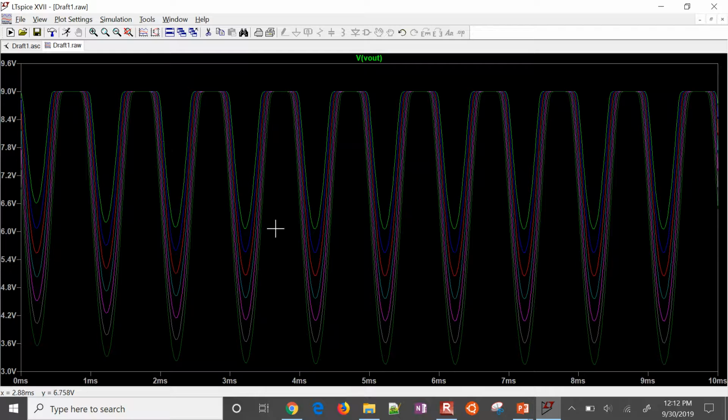So in summary, we are trying to keep it in the active region, which we're mostly in the active region right now, and you'll want to meet all your specs for lab 4, and you want to take a look at your headroom so you're not hitting your rails, so that you can get a good output.